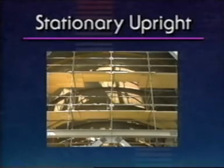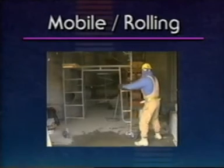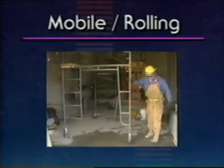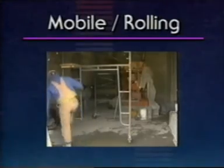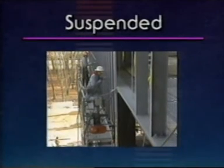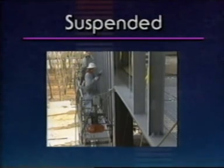Stationary scaffolds are fabricated as a framework of wood or metal supports and may be extended as the work moves higher. Manually propelled mobile scaffolds, sometimes referred to as rolling towers, are also constructed of wood or metal. Mounted on wheels or casters, these structures can be moved from place to place. Suspension scaffolds, such as the one Robert Smith and Jose Medeiros were using to paint the bridge, carry a working platform suspended on ropes or wires attached to a structural member or an outrigger beam above.